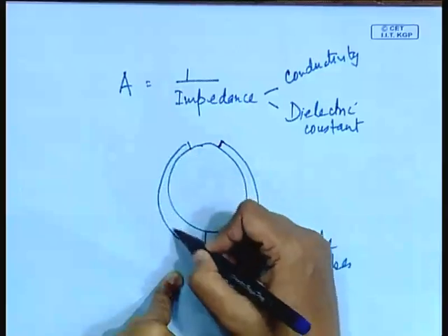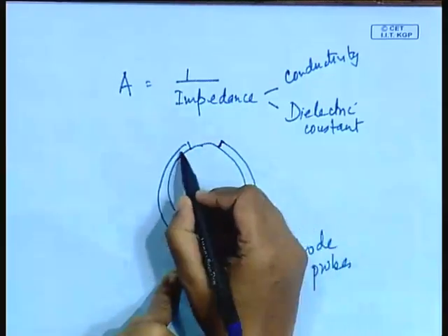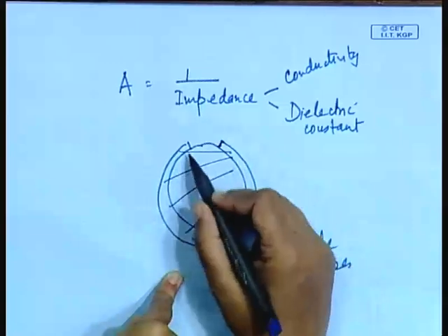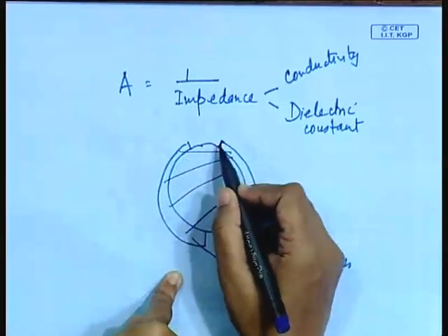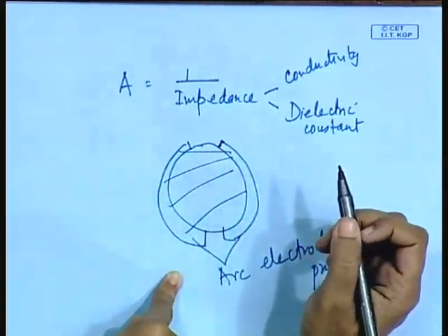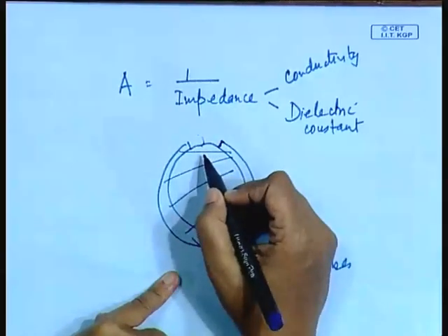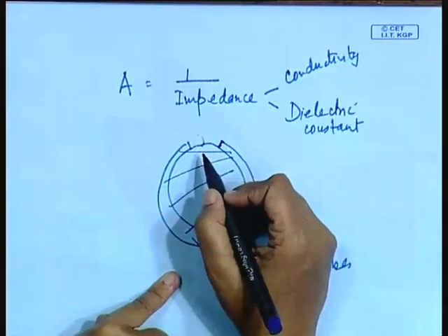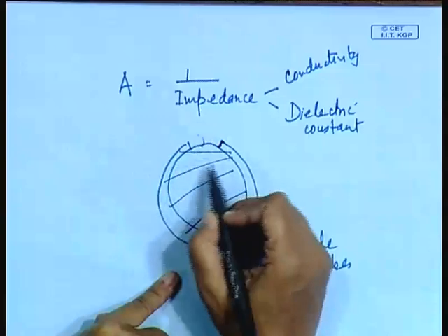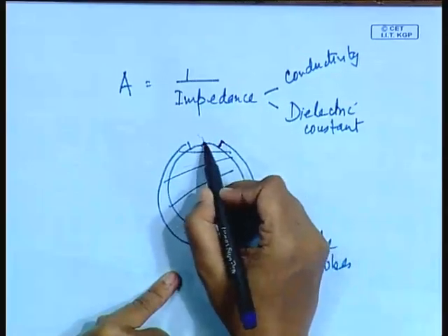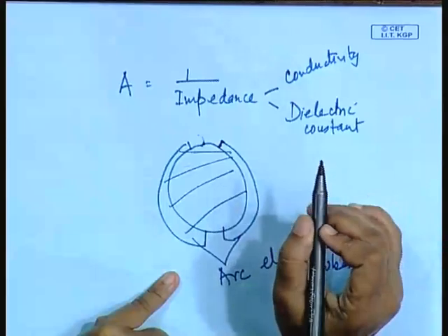They span the entire tube wall, and through the electrical lines they give us an idea about the area average void fraction. There are definitely some problems here. The most accurate result we would get is if the entire cross section is covered, but that is not possible, because we have to ensure that the electrical path goes through the two phase medium. So, if the electrodes touch here, then the thing is gone, remember that.